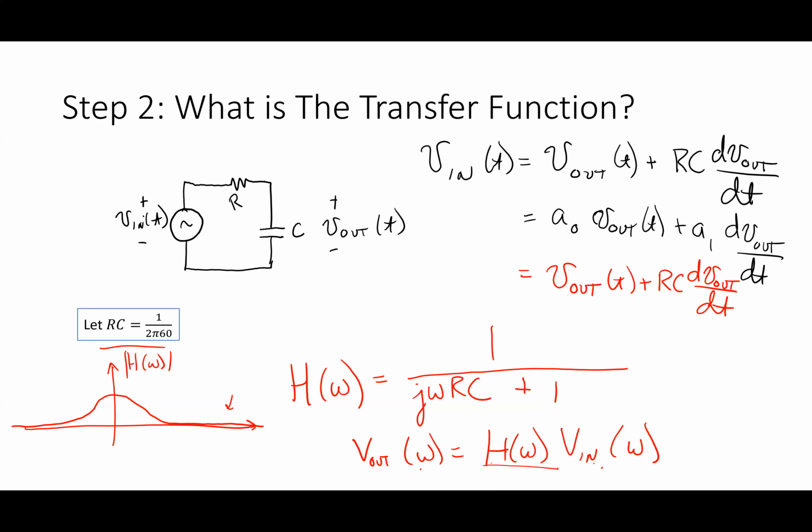So no matter what input I put in, am I going to get an output? No. So this is a low pass filter. Low frequencies make it through, high frequencies don't. That's our concept. We don't say they don't make it through. Typically we say they are quote unquote attenuated, which means they're made smaller. In the context of filtering, we'll say stuff passes or it's attenuated. Attenuated expresses the fact that it's reduced. In other words, if I put in 1 volt, maybe I only get a millivolt out. That's the meaning of attenuating.